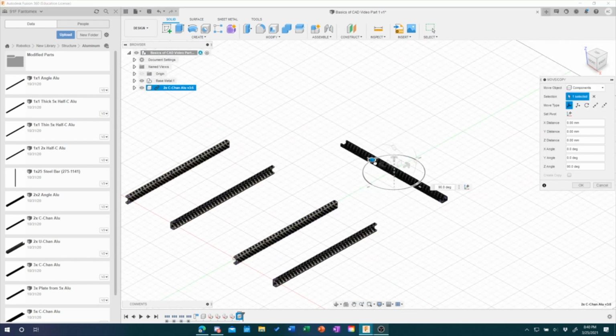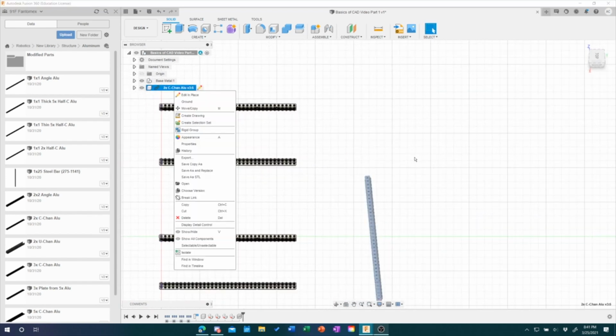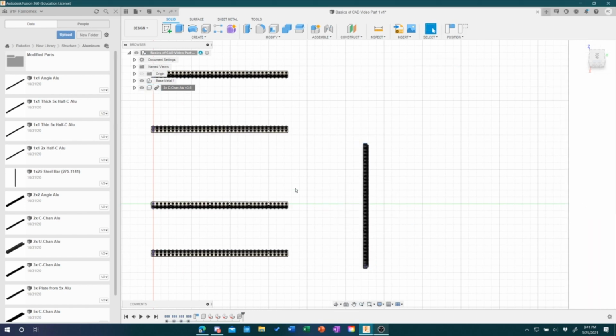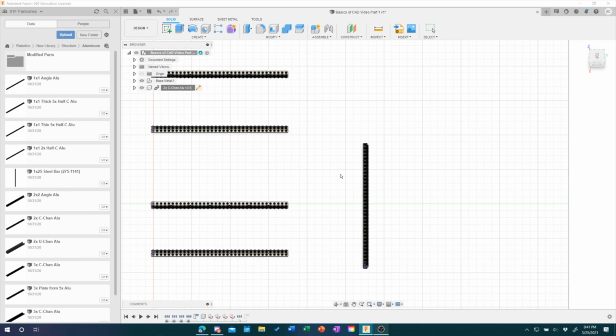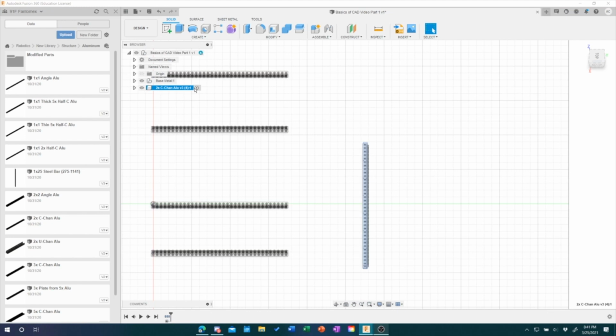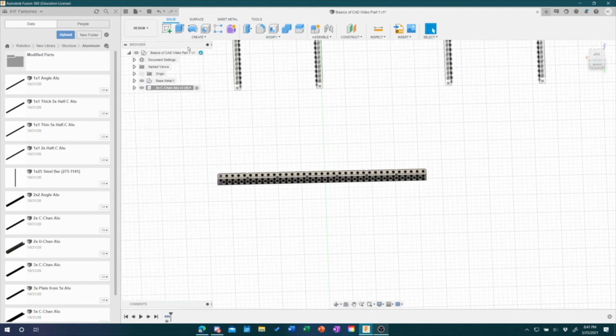However, you may see that the library has no 27-hole C-channels, so you would have to cut it virtually. Many people have different ways to cut their C-channels, but the way that my team and I do it is by activating the component we want to edit. That way, any cuts that we make are only on the component and not on any others. To activate the component, hover over the piece in your tree and click the circle on the right-hand side of the component so there's now a black circle filling the circle. You should now see that the original 4 C-channels you brought in to be ghosted.